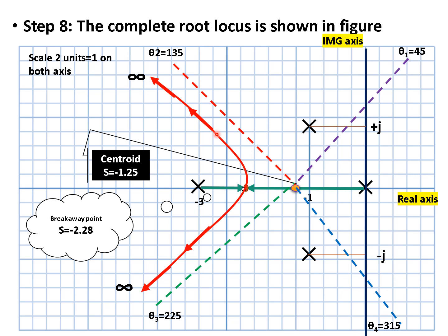The next thing is we have already calculated the angle at which it touches the imaginary axis, that is plus j 1.09. And since it's a complex conjugate, we need to find the angle of departure. The angle of departure obtained was minus 71.56. Now how do we write this?